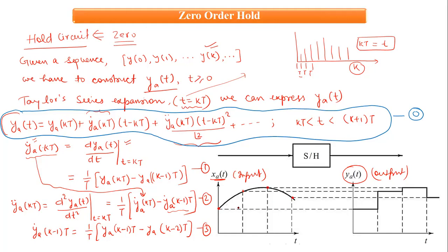Now this is an analog signal converted into sampled, quantized, discrete, and digital. Now we have to convert this back to the analog form. What we will do is hold this sample till the next sample value arrives. As soon as the next sample value arrives, the output will jump or fall to the next sample value. Similarly, this sample value will go as it is till the next sample value arrives, and so on.